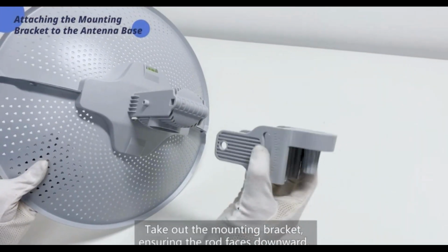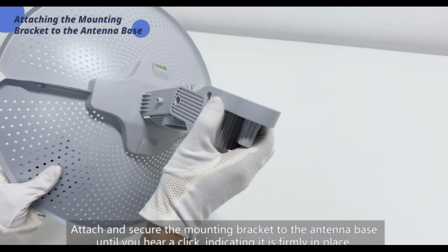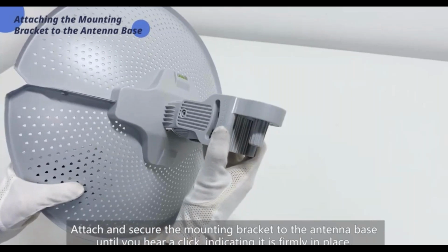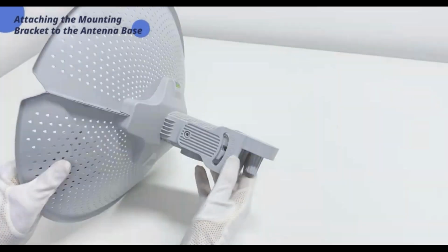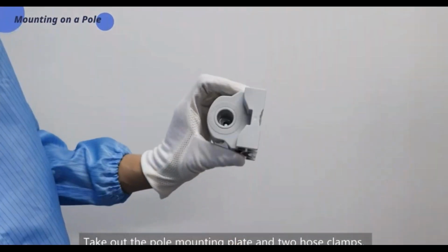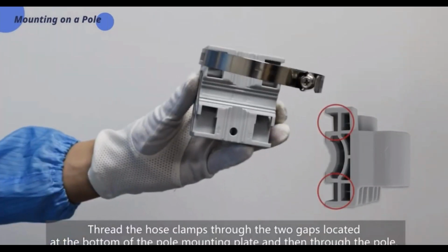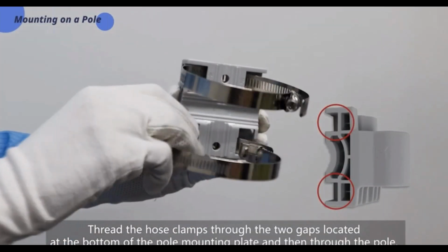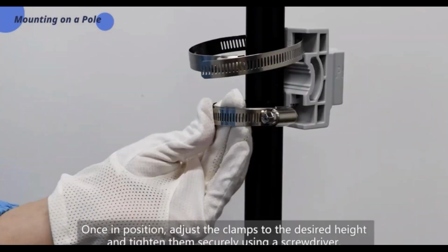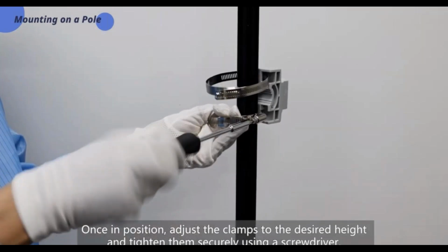Take out the mounting bracket, ensuring the rod faces downward. Attach and secure the mounting bracket to the antenna base until you hear a click, indicating it is firmly in place. Loosen hose clamps with a screwdriver. Take out the pole mounting plate and 2 hose clamps. Thread the hose clamps through the 2 gaps located at the bottom of the pole mounting plate and then through the pole. Once in position, adjust the clamps to the desired height and tighten them securely using the screwdriver.